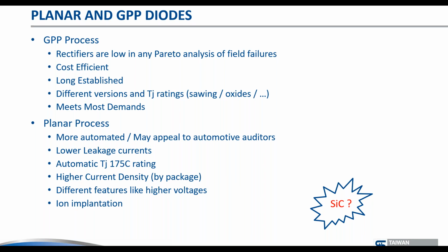So if you are really squeezed on efficiency, and if the 0.6% of efficiency losses that the bridge causes is important for you, please talk to us about these LLD diodes, because we can maybe help you.